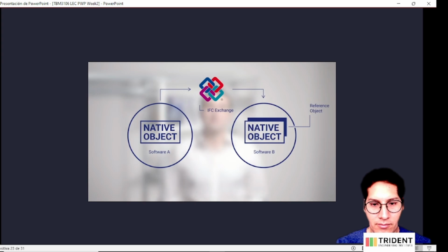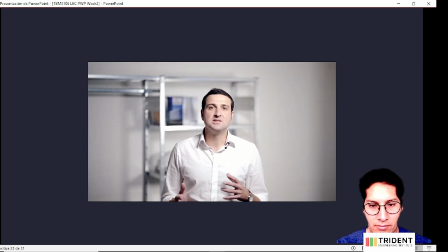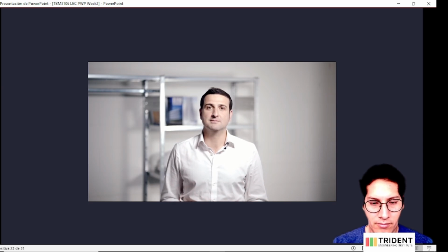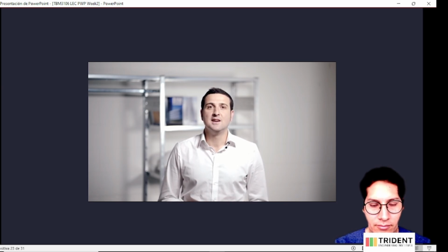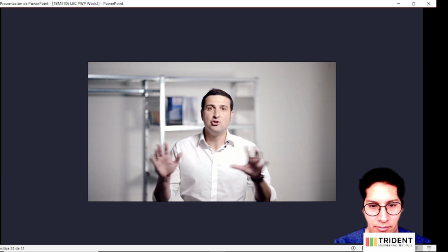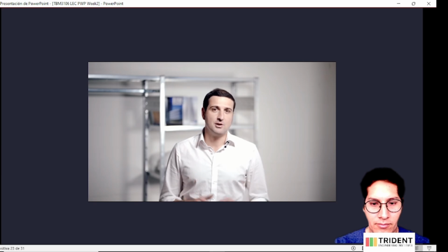The current IFC workflow doesn't support data exchange to the extent that I can start modelling in one software, make an IFC export to another application, and continue modelling uninterrupted. It's more accurate to think of IFC as a means of referencing or archiving model content. In the previous video of this series, we presented IFC as the PDF of BIM. Like PDF, an IFC file is a frozen copy of the original content. It can be viewed, measured, used for clash detection, cost estimation or simulation, and innumerable other uses, but should not be edited.